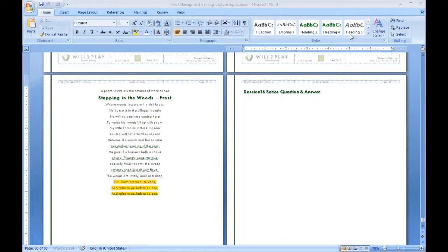Session 3, central file, local file. What are you going to do with that? Setting up, naming convention. Let us take this and deal with this one issue now, because this is important. So in 2010, has anyone made a final decision on what their central files shall be called? The question becomes, because it used to be like project name _ central file .rvt.